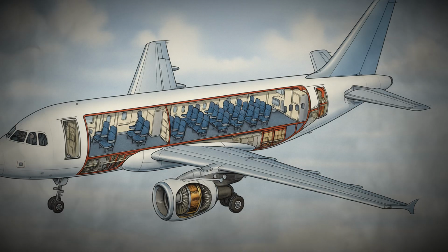Aerodynamics itself is a source of safety when properly understood and applied. Engineers design airplanes to have stable handling characteristics, making them easier to fly and less prone to dangerous oscillations. Automatic systems such as yaw dampers prevent Dutch roll, a type of instability that can occur at high speeds. Stall warning and protection systems alert pilots before dangerous conditions arise, and can even apply corrective inputs automatically. The balance of lift, weight, thrust, and drag is constantly monitored to keep the airplane within safe limits.